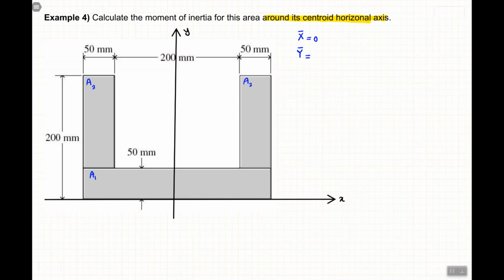All right, because basically they are at the same level. Now for each of these areas we know where is the centroid. For the A1 we know that the centroid is this. What's the coordinate for this system? X is 0 and y is 25. So see, the good thing about picking the y-axis to pass through the symmetric line is that dealing with 0 numbers is easy here, rather than just writing what is the x and so on.